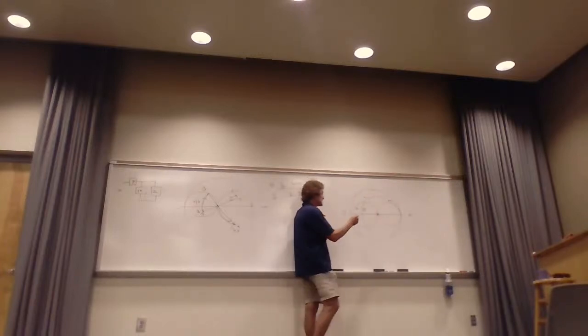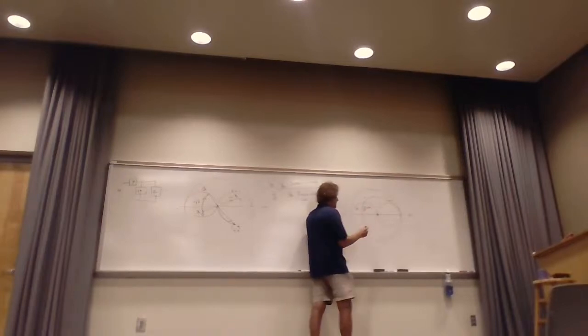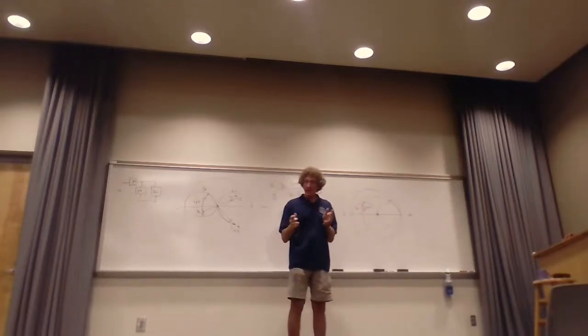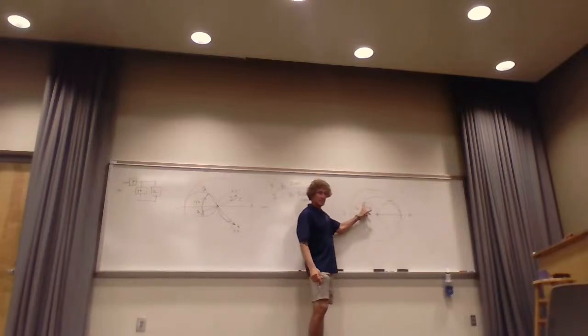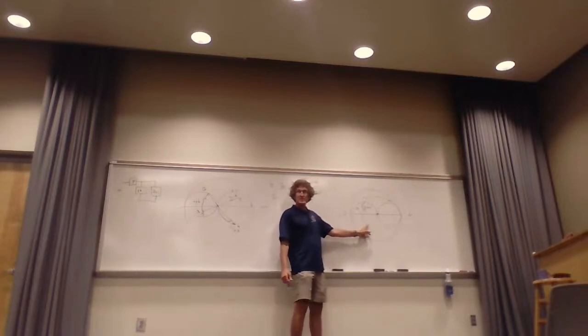Now, this right here is going to have R plus j alpha, doesn't matter what you call it. I can add a plus impedance, which would be adding an inductor, right, at j omega, and I could get to this point, right? That's where it would be nice, right? Or if I wanted to in series add a minus j something, I'd add a series capacitor and I could get to this point. Does that make sense to everybody?